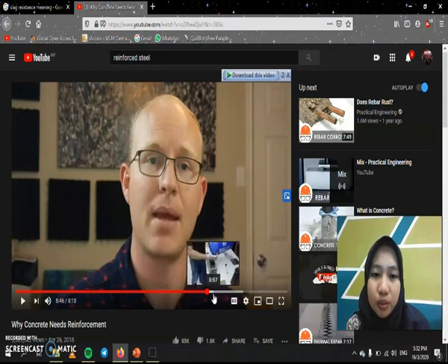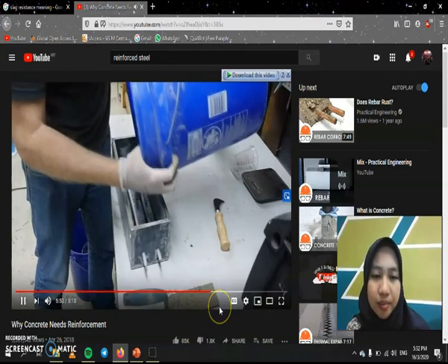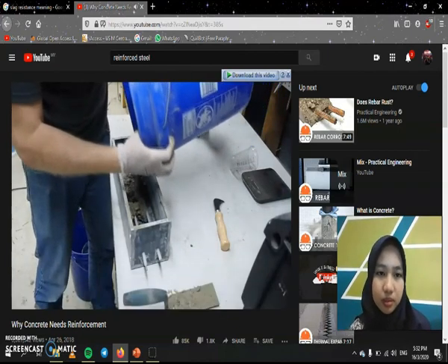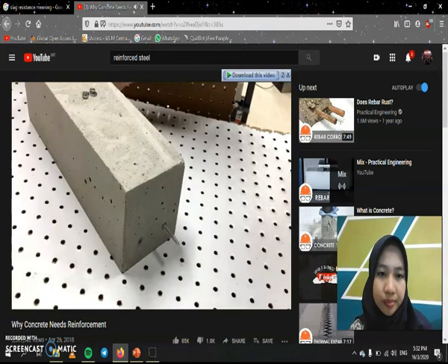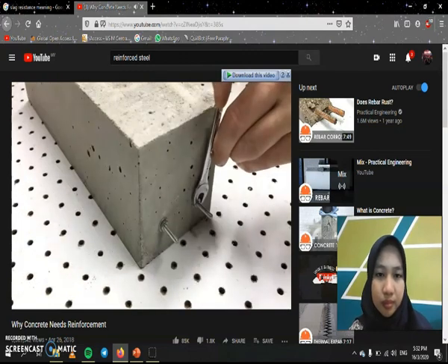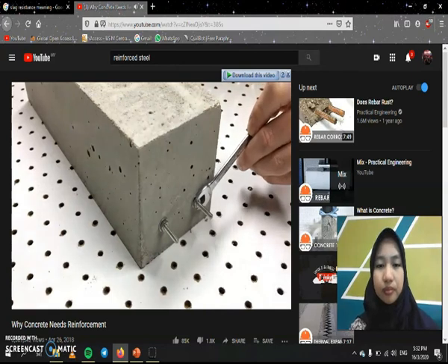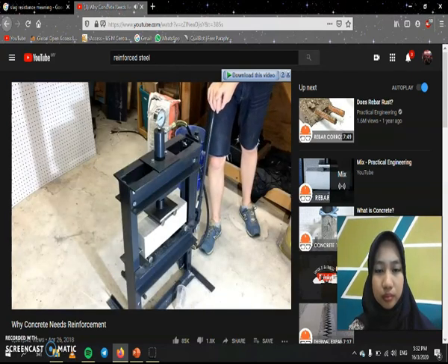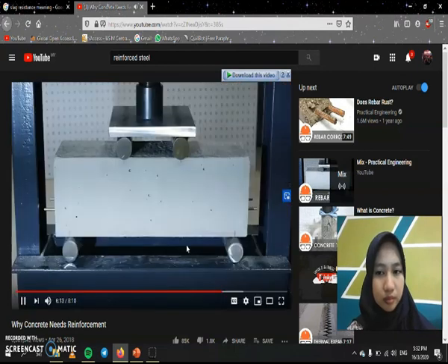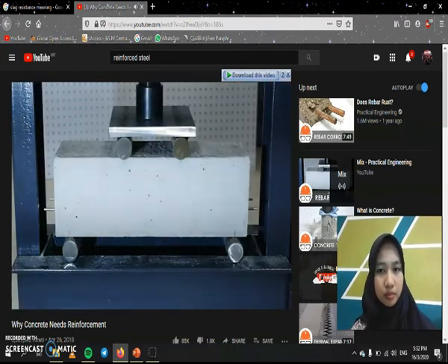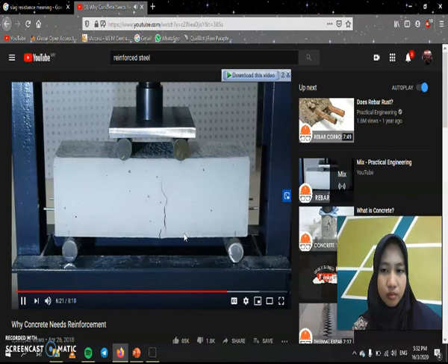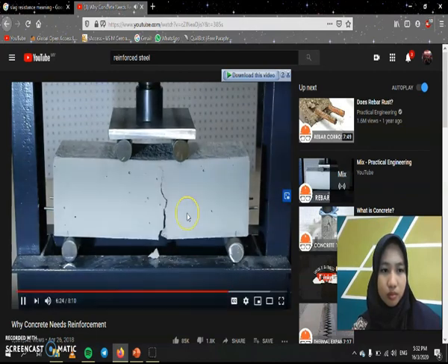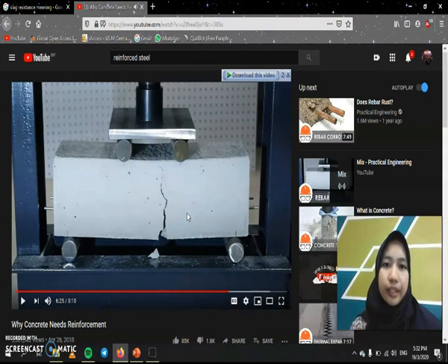And now for the post-tension. In this method, the stress in the reinforcement is developed after the concrete is cured. For this next sample, I cast plastic sleeves into the concrete. The steel rods can slide smoothly in these sleeves. Once the beam cured, I tightened nuts onto the rods to tension them. Under the press, this beam wasn't any stronger than the conventionally reinforced beam, but it did take more pressure before the cracks formed. Also, this one wasn't quite as dramatic because instead of the actual steel rods failing, it was the threads on the nuts that failed first. Alright, that's all from me.